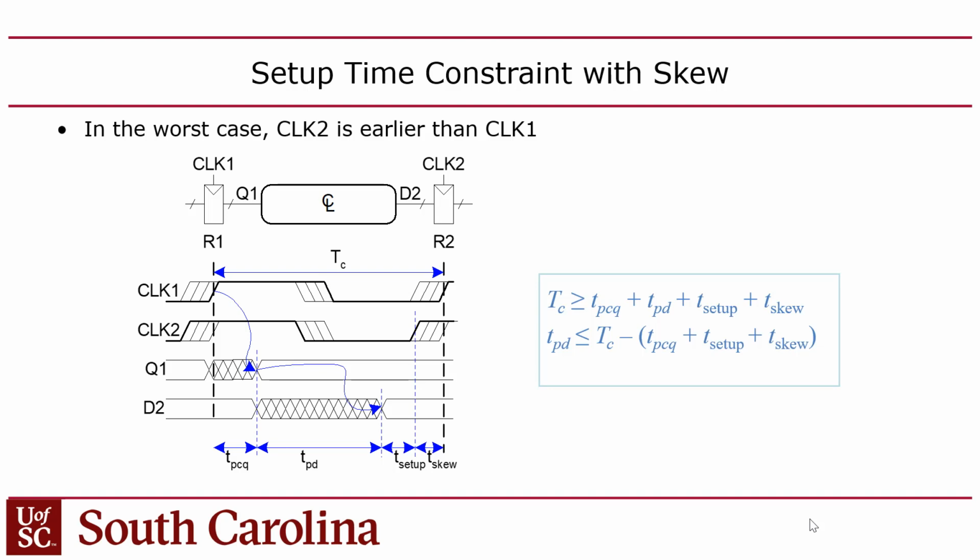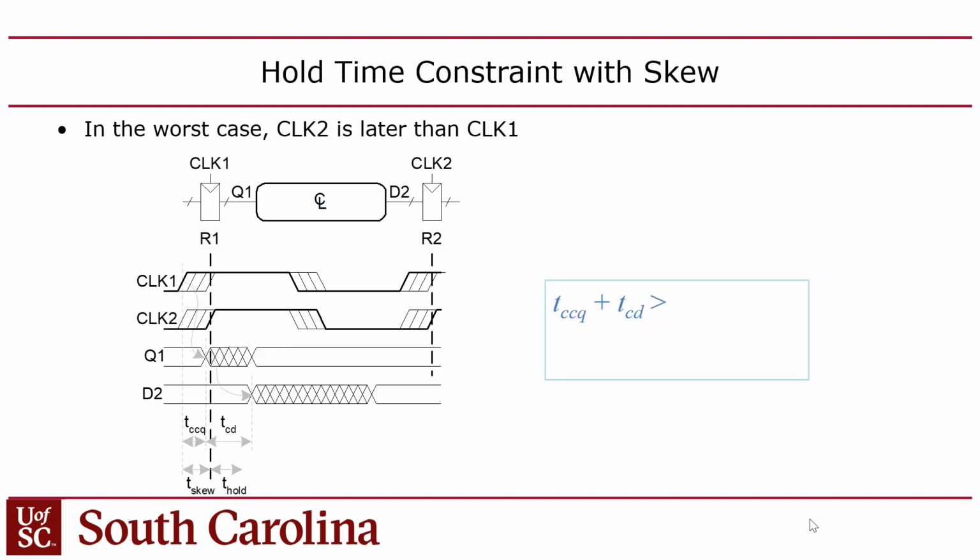You guys with me? Which means sometimes it'll tell you that your F max, meaning your minimum clock period, you might put this on the FPGA and it'll say, oh, you can run it at 200 megahertz. Sometimes you can bump it up to a little higher, right? But it's risky, right? The timing analysis is pessimistic. It's trying to guarantee that you'll never have metastability, right? So the FPGA tools will give you the safe number for the clock.